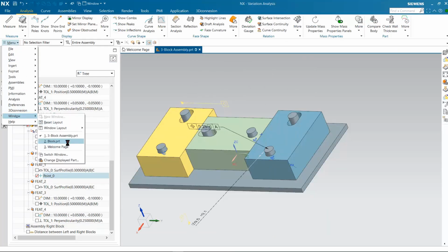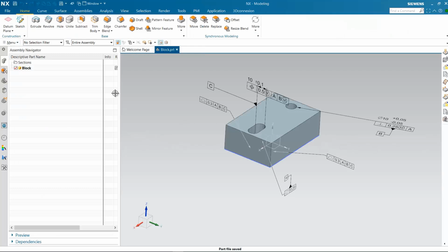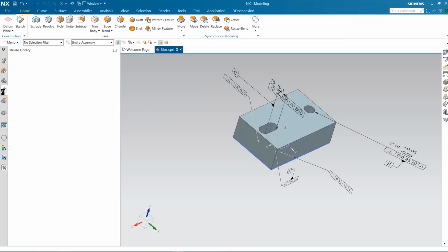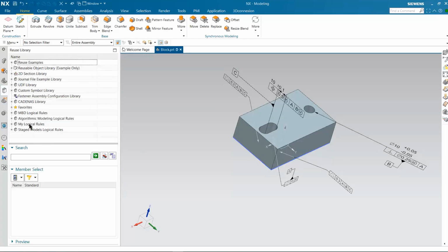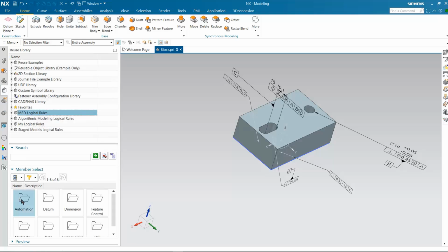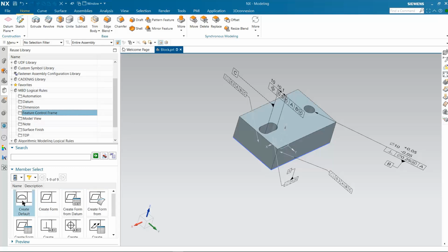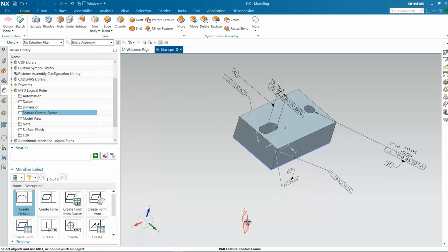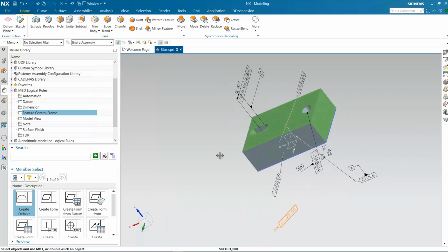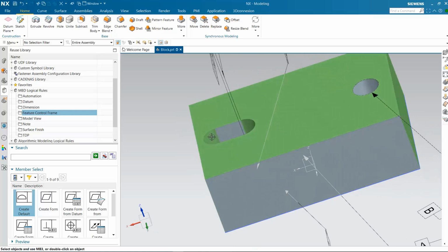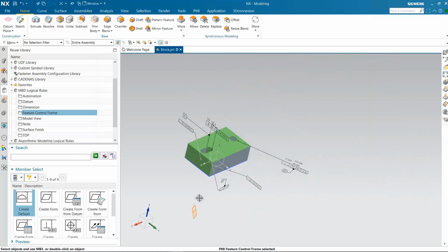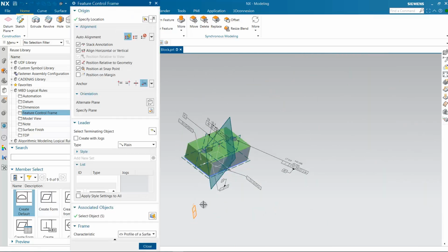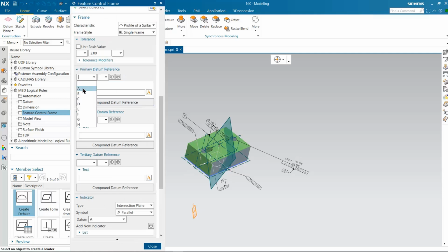One more thing, we now need to add those otherwise unspecified tolerances to the 3D model for them to be used in some downstream applications, such as first article inspection. Once again, the newly available NX MBD can do the magic here. I am using this rule to create a default surface profile on all untoleranced faces. You can see 5 additional faces are now toleranced. I can still go in there to edit the tolerance, say to add datum references A, B and C.